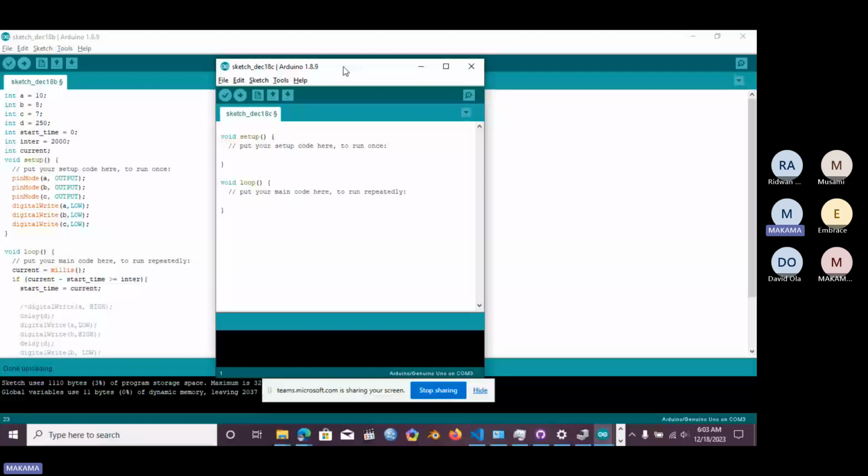So you need to define your pin. Let's call it LED pin, 13. We don't need a library in order to use the millis function. We need to do some initialization, which is to specify our pin, the LED pin, as output, so that the Arduino will know this pin will be used as output. But initially, let our output be low.